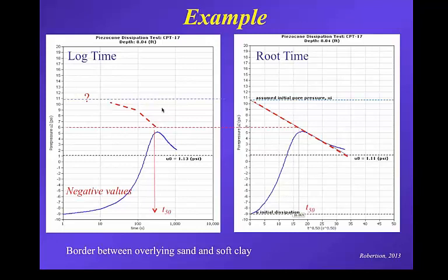But there is somewhat of a move that people are tending to lean more towards a smaller strain G. I wouldn't go as far as saying that the G0 or Gmax over Su is the correct one, because those numbers seem too big. From our practice, those numbers would appear to be too big. And typically, I would drop those numbers often by about a half or a third to get to a more representative strain value, which clearly depends on the rigidity index.